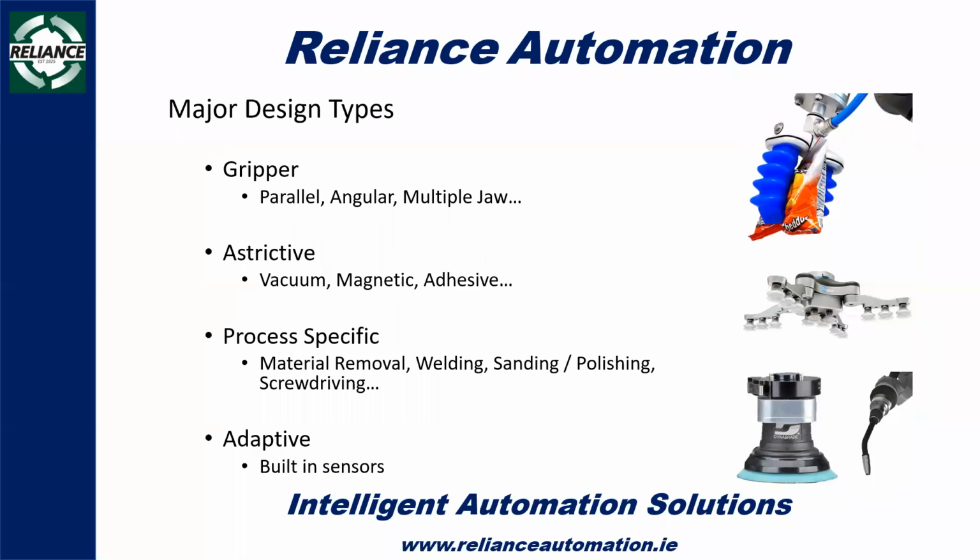So once we've defined what the part is and the size and the weights, etc., then we can have a look at the types of different grippers that are out there. I suppose there's three or so major types. The first being the traditional gripper. This is probably the oldest type that's available now. It comes in parallel sides, a couple of fingers typically, but these can be adapted to be 4 fingers, 3 fingers, 10 fingers, depending on the size of the part that you're picking up. And they also can be angular, circular, depending on the part that you're picking up.